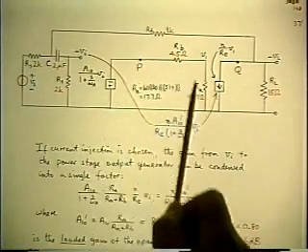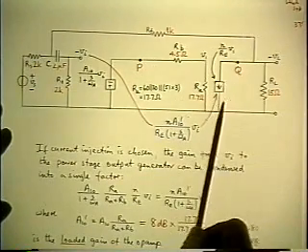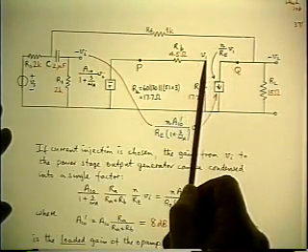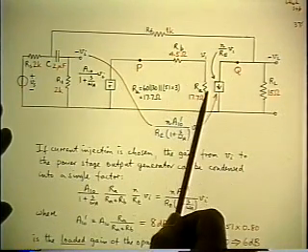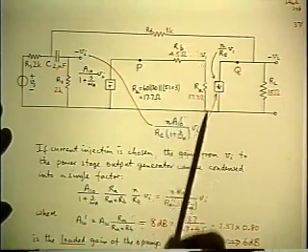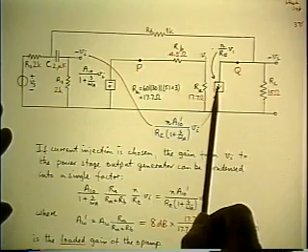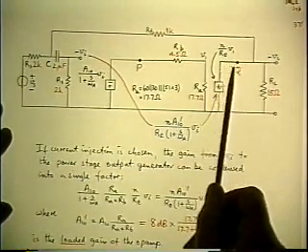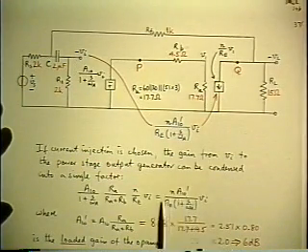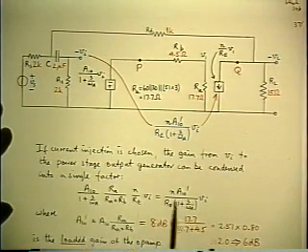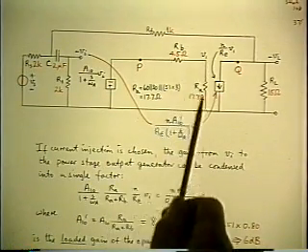Basically what we do is we simply solve that internal loop once and for all and get rid of it. Which means that V1 is equal to this coefficient times VI times this resistive divider ratio, RA over RA plus RB. So if you simply make that substitution, you can label this generator as a function of VI instead of a function of V1, and the function is this, where I've simply redefined A10 prime as being the original A10 times the resistive ratio.